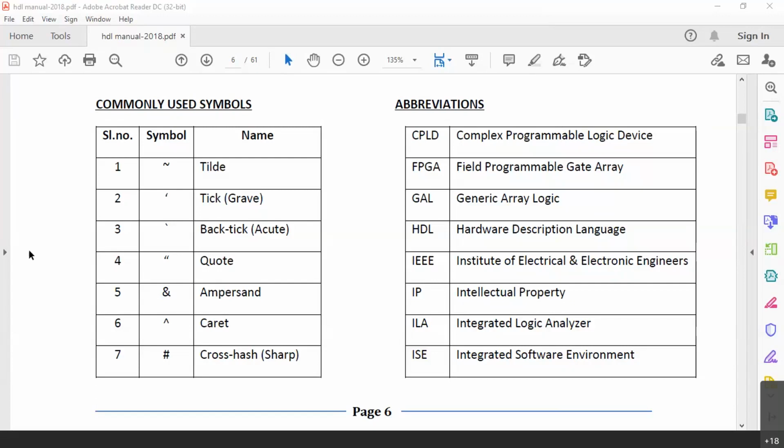So in Verilog, there is no choice of library as such. We don't specify any library, because the library is built in. Whereas in VHDL, we specifically tell a particular library, and we specifically tell which package we are using. That is because VHDL is a very vast programming language. That is the idea. I hope I answered your question. Any more questions?